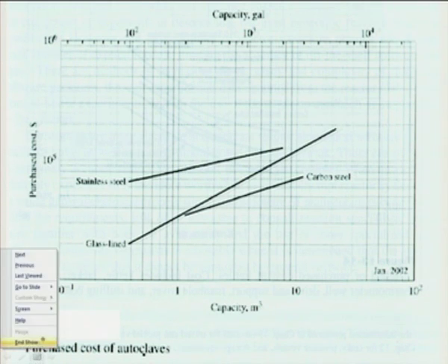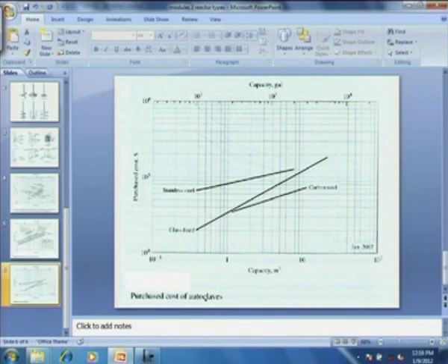So do calculations, estimate the volume of the reactor. Then depending on what kind of reaction you have, you have to select the material of construction. That is another issue that again will be covered in the courses of safety and risk assessment. We are going to have a brief introduction of it. There are several grades of stainless steel, 304, 306, depending on the temperature and pressure. Corrosion tables are available, which give the extent of corrosion that occurs in a reactor over a period of time, and then you have to choose a proper material of construction for the reactor operation.